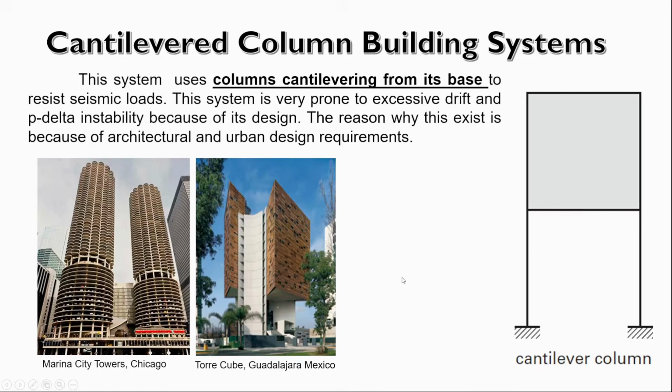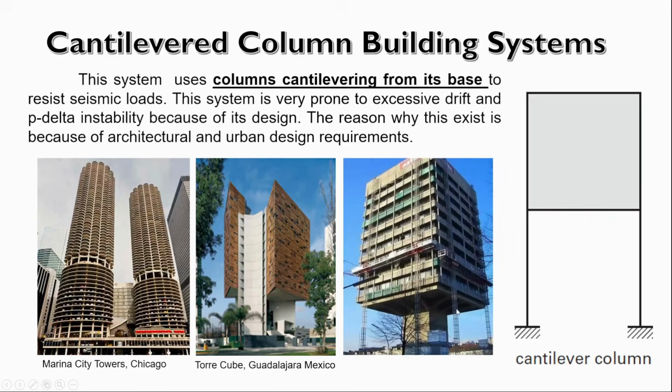And I found this picture on the internet. I think this also exists. So you can see here we have a very large column cantilevering from its base, and I think this can be done, but always remember that cantilevered column building systems have a very, very low overstrength factor. So anyway,